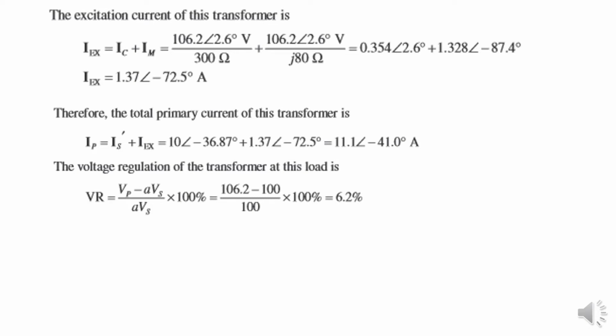Before going into the equation, we'll see what voltage regulation is. When we have a load, voltage regulation is calculated as a percentage. It is actually no load voltage minus full load voltage, divided by full load voltage, right?